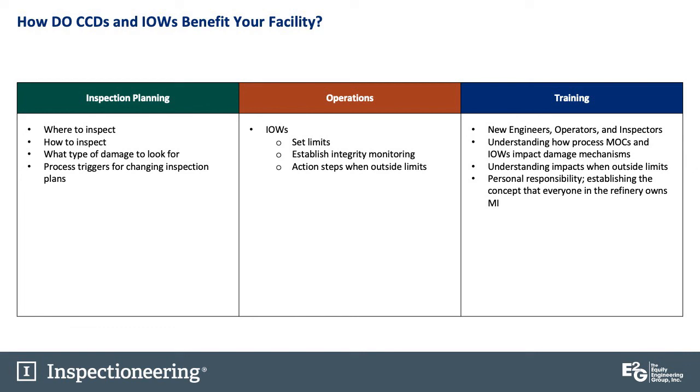For operations, it provides you knowledge on IOWs, what the limits are about, and action steps to take when operating outside those limits. Training: CCDs and IOWs are a good training tool for essentially all new engineers, operators, and inspectors. You'll have different levels of training depending on the personnel.